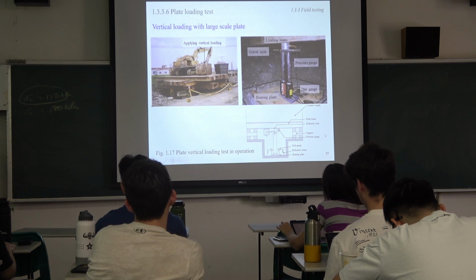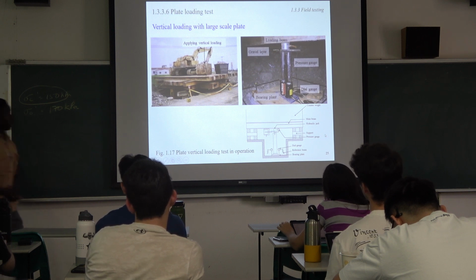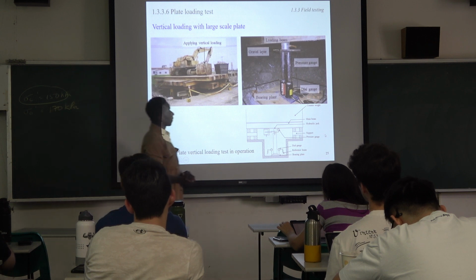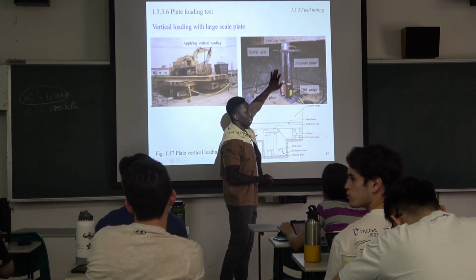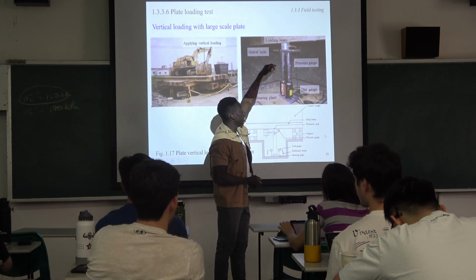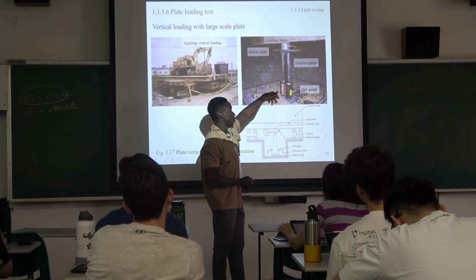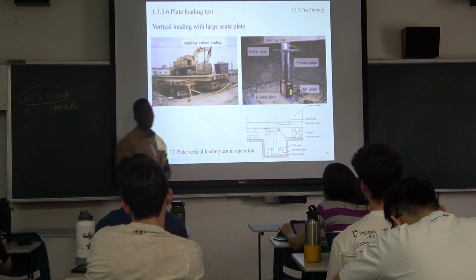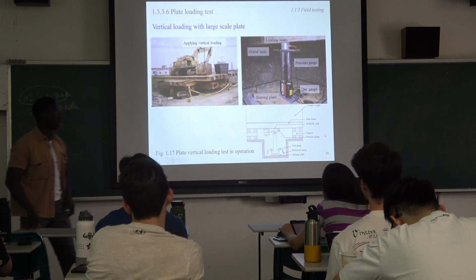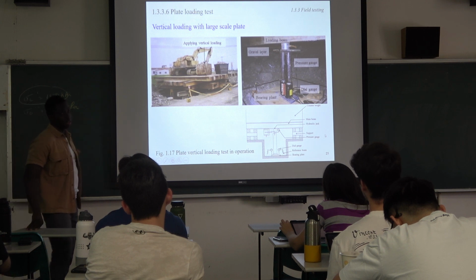Okay, and this one is the plate loading test, and it should be similar. So in this case, you have a base plate, and then this one is like a hydraulic jack, and then it will apply a lot of force on this soil at the bottom, and then determine the value of the force at which the soil underneath fails.